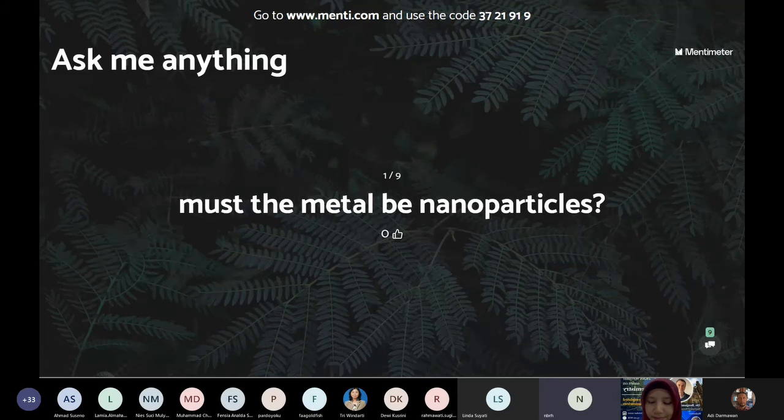I have to say that we find that it's actually harder to make metal nanowires by this method than it is to make polymer nanowires, and that's probably because of the surface tension. So the copper nanowires that we first made about 10 years ago, they're really not conductive at all, and it took quite a lot of effort to find ways to force the copper to make a smooth nanowire, because metals like that have very, very high surface tension, and so they really don't want to be nanowires. They'd much rather be nanoparticles. You have to reduce the surface tension somehow. Yep. Okay, next question.